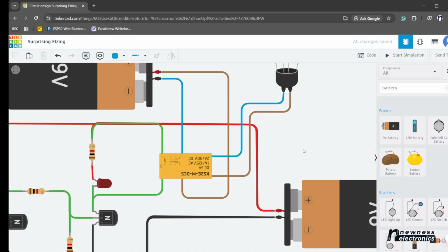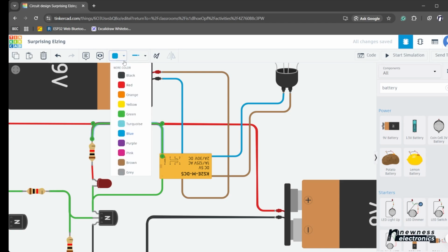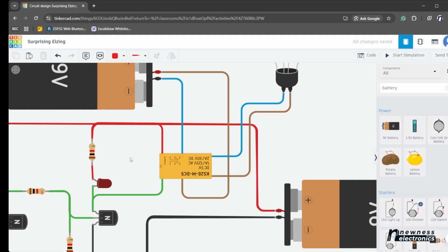Now, before you power on these circuits, you can't directly connect a relay to your transistor in this manner. It will blow up your transistor. Do you know why? There's something called reverse current that's peculiar to coils. So in this relay, there's a coil.